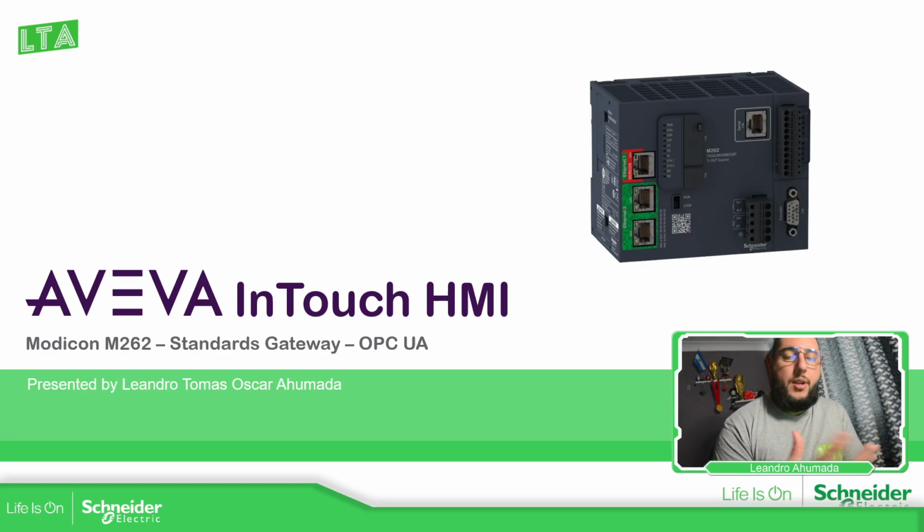So there are different ways to communicate and share the values from the PLC to the AVEVA InTouch application. In this particular video, what I'm going to show you is how we can use the OPC UA. One of the main reasons is because the OPC UA is the easier one that we have on the drivers for the AVEVA InTouch.